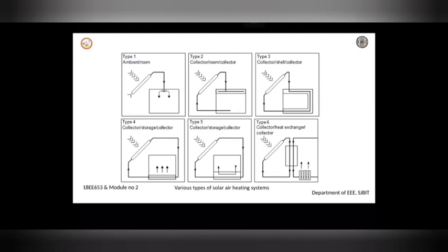This system with a forced ventilation fan provides the best efficiency and thermal output. If I have an additional fan connected here, I can suck or remove the air from the ducts. By using this, I can improve the overall efficiency and the thermal output will be very good. So this may be used for large buildings with large surfaces which serve as radiation sources.